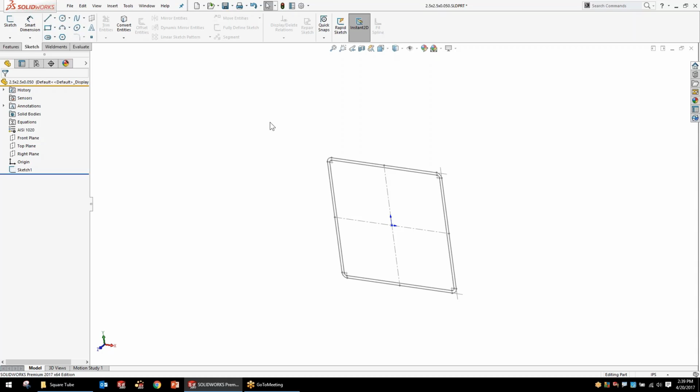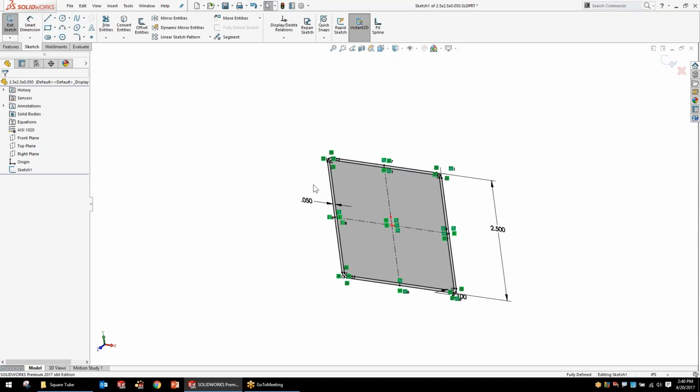So some of the toolbox items or features, or in this case a Weldments profile feature, maybe some of the routing or tubing and such, sheet metal, they've all got little SOLIDWORKS library features assigned behind the scene working with them. So here the big step is we need to make sure that we are not working and editing the sketch. We need to step out of the sketch, so make sure that you exit the sketch.